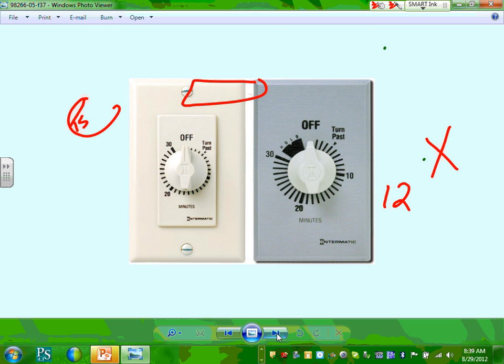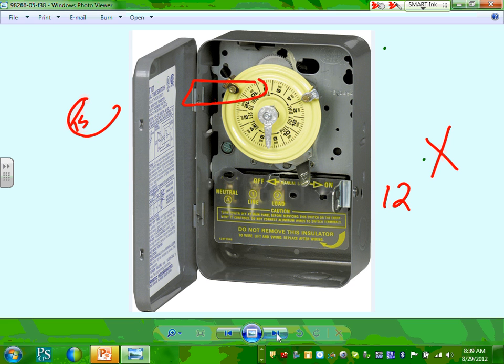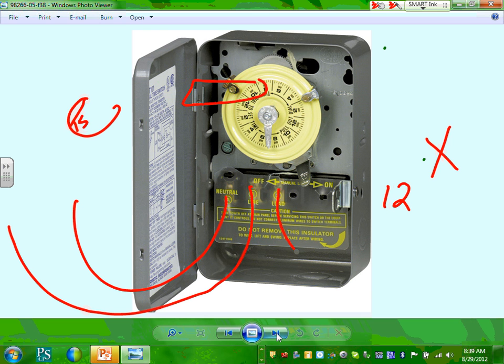Okay. A couple of dimmers, guys. Here's a couple of dimmers. Dimmers are on, off. You have line, I don't know if you can see that. You have load and line coming in and a neutral. So you bring your hot in, in this case, and here it's coming in and then coming out, and a neutral. And here's my fixture. And you set your timer.